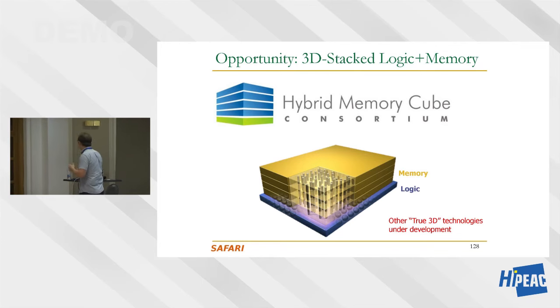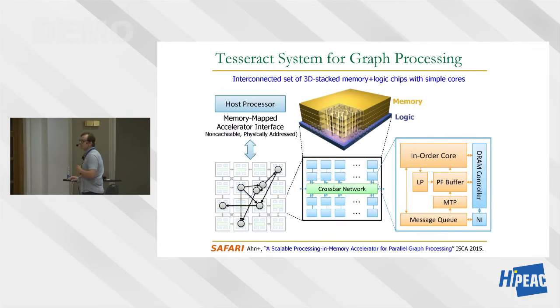So okay, basically we're going to do computation in the logic layer. This is a huge system design paper, and the idea is, in the logic layer we're going to divide into what's called vaults, and these vaults have DRAM controllers and also a simple in-order core to do computation. It's actually a very general purpose system, although we use it for graph processing. You could use it for machine learning as well. We may get back to that. Each vault controls and owns the memory stack on top of it.